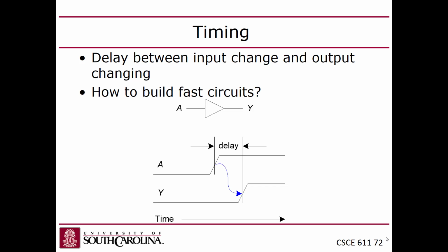The gate is, by its very nature, a capacitor, because the principle by which transistors work is that the gate is a conductor, a dielectric, and then a conductor. So it's a sandwich, right? The top is polysilicon. The bottom is the channel, the semiconductor. And when you charge up the gate, it attracts minority carriers into the channel, through induction. Right, you guys with me?